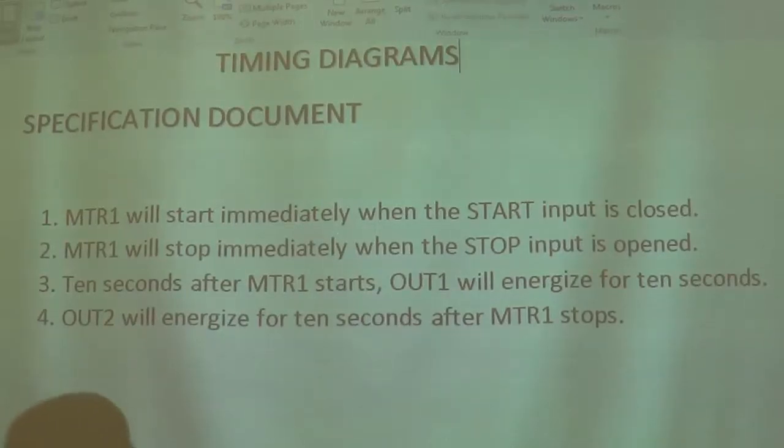All right, we're going to talk about timing diagrams and how the timing diagrams will go to the ladder logic, but first we'll start with our specification document of what we want to do. Simple process. Motor 1 will start immediately when the start button input is closed, and it will stop immediately when the stop input is closed.